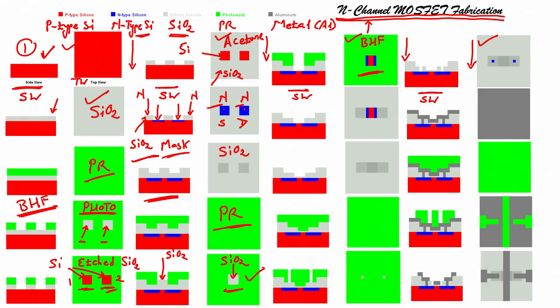What you can see? You can see on the cross section, you can see the photoresist is there, the gate oxide is there, here gate oxide is there, here there is no oxide. You see in this region there is no oxide, so we can directly see silicon. This is what you can see here, right. What you can see, that there is an n type in the center, there is silicon, you can see silicon, correct, easy.